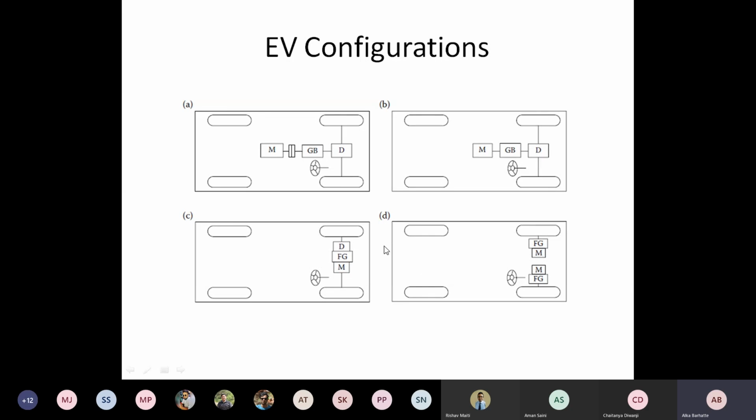After that, it has been observed that we can use an individual motor for each wheel, and individual wheel speed can be controlled by controlling the motor speed, based on the steering position and the position of each wheel.